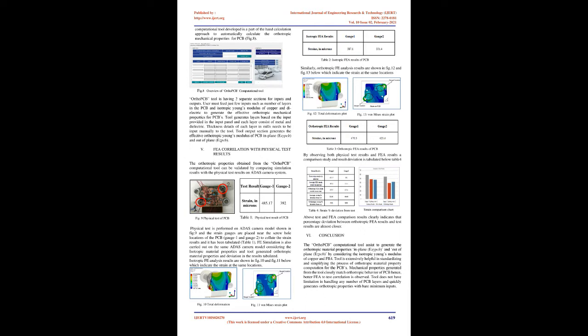Prepreg material is made of similar material as the core material but is in a soft, pliable form and comes in standard-sized thin sheets. Copper foil is a thin sheet of copper that is placed on or between prepreg materials and bonds to the prepreg with the adhesive that is part of the prepreg, as shown in Figure 6.